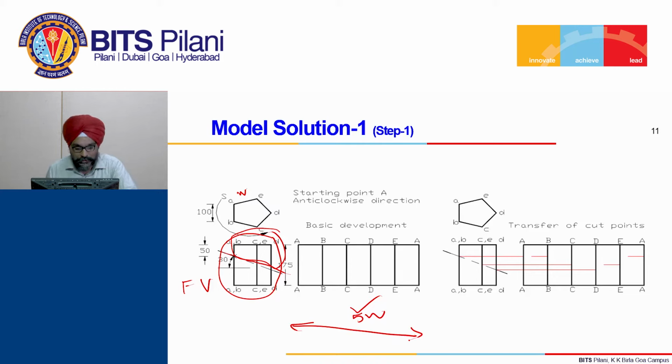One after the other you can use the mirror command, or you can use the array command also. These lines can be arrayed at a specified distance, and finally, the last and the first one can be joined. You can apply your own shortcuts or tricks. A video on how it can be drawn using AutoCAD is also available, you can look at that.